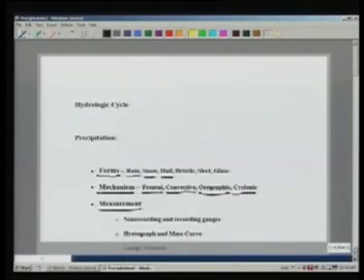topic which we discuss is the measurement of precipitation. There are basically two different types of instruments which are known as rain gauges. One is a simple non-recording and the other is a recording. Non-recording means that it will not record with time a continuous variation of rainfall. We will go manually and maybe once a day see the instrument and see how much rain has collected. And in recording type gauges, we have a continuous record of rainfall. As it is falling, it is being recorded.